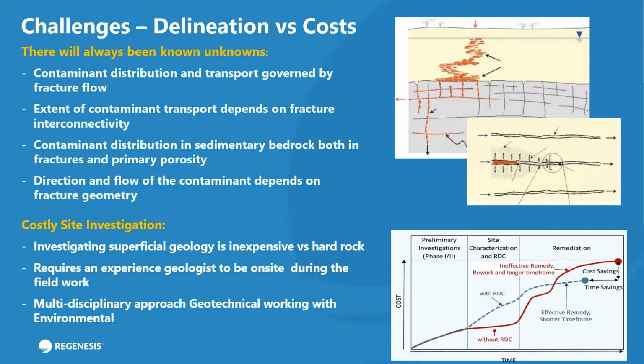Something I will stress is that for these fractured bedrock sites, you do need an experienced geologist to be there logging those cores. It's fairly standard in our industry that brand new graduates are the first to be sent out to site. It's important that they are 100% billable, but they may not have the experience of working in fractured bedrock settings. So I would always stress, if the budget allows, do have somebody more experienced on site. If you can, get them both on site, so there could be some cross training, so they can understand what they're looking at and what they're logging.